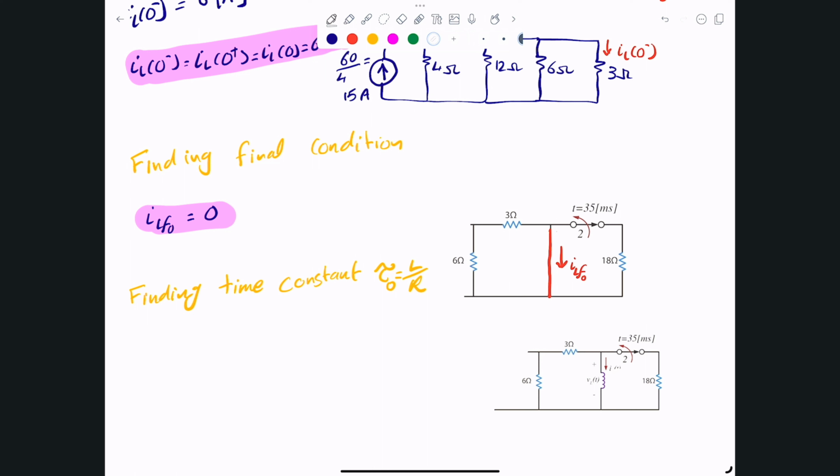And what we're interested in is the point in here. So I'm interested in the Thevenin equivalent for the circuit from this perspective in here. Really what I'm after is the R Thevenin that we can see from here. V Thevenin, by the way, will be 0 in this particular case because there are no sources. But anyway, what we're after is R Thevenin, or the R seen by the inductor from here.